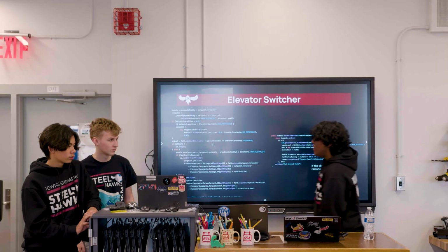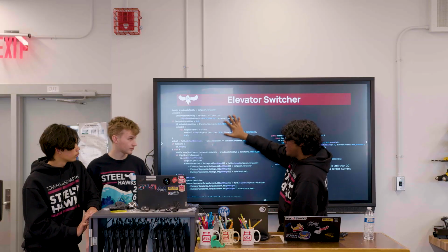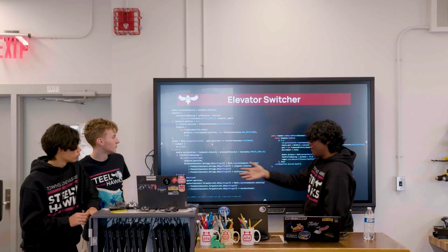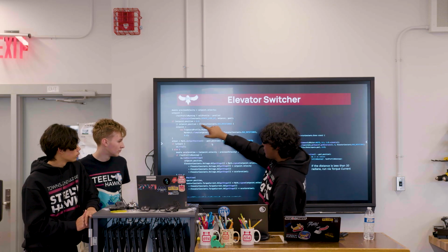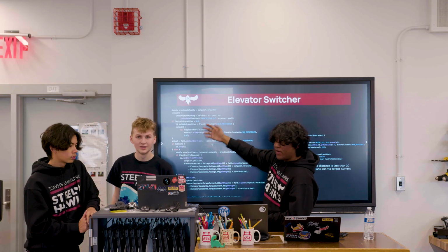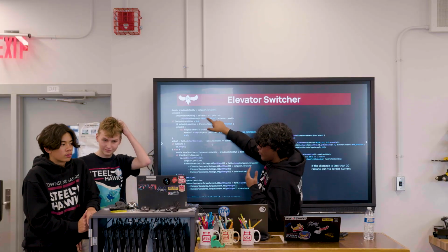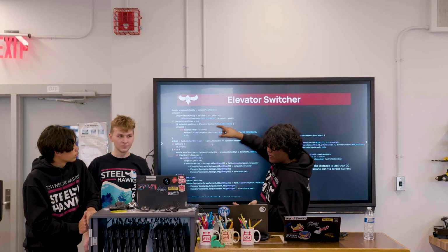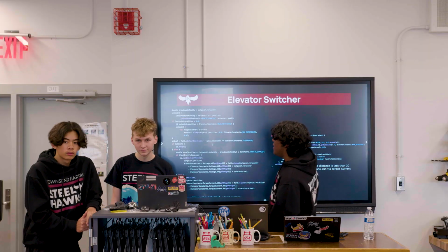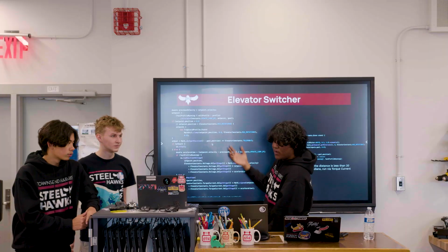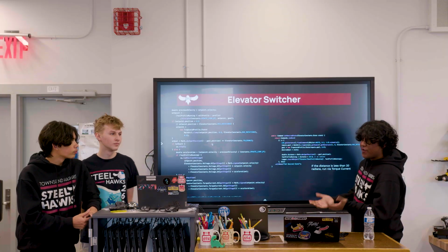Now we're going to get into our first part of the code. You can ignore the previous velocity. That's used to calculate a derivative to find acceleration, but you don't have to worry about that. We calculate our set point using a ternary operator. We check if the fast profile is running. If that's true, we calculate using the voltage profile, and if that's false, you go back to FOC and use the FOC profile. Then your set point is where you want to be, and your goal is just your previous goal.